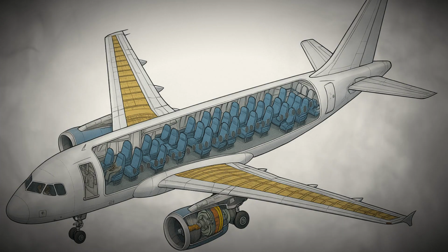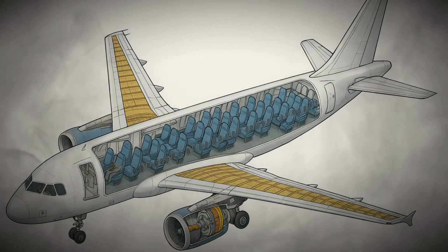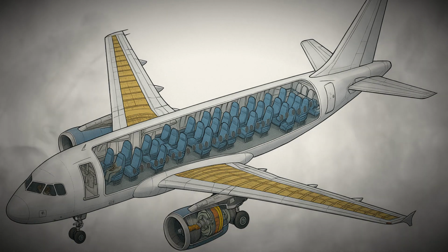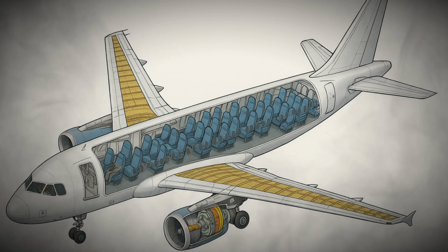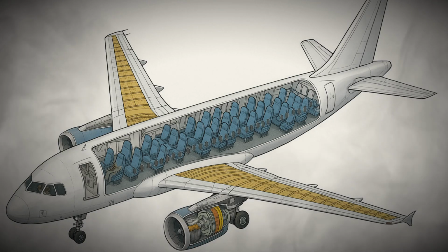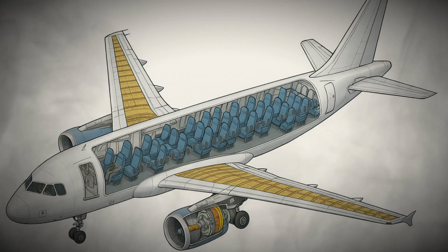Takeoff requires careful control of pitch to avoid stalling by rotating too steeply, as well as close monitoring of engine performance. Crosswinds must also be managed, with rudder inputs ensuring the airplane maintains alignment with the runway during the ground roll and initial climb. Engine failure procedures are rehearsed by pilots repeatedly in simulators, because the loss of thrust during takeoff is one of the most critical emergencies.